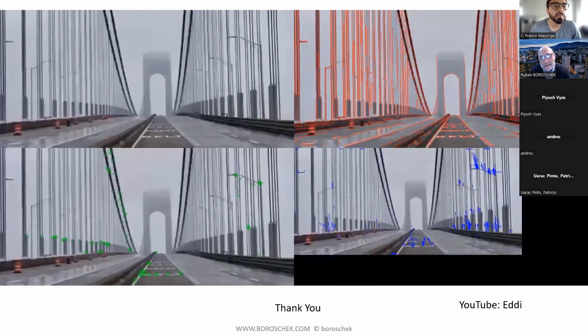The software I have in mind is quite expensive. The problem with this software is that you have to be an experienced user. You have to understand what you're looking for, and you have to understand sensors and noise level in sensors. One of the reasons this black-boxing is not here yet is that if you go beyond just monitoring the period, which can be done by most civil engineers, you just put a sensor, do a crude Fourier transform, and choose the maximum value. And if you're smarter, you do a Welch type of averaging of the frequency content and get a better estimate. So we have many companies that do just period detection and amplitude detection.